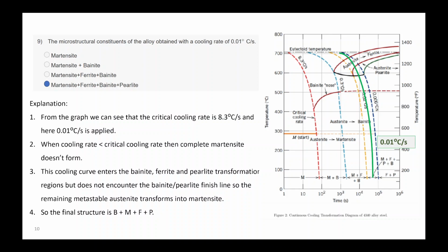Ma'am, in that metastable state, the statement was actually given: it is actually a non-equilibrium state, but with a very long time for changes to occur. When we take that martensite is actually a metastable state, isn't it? So in that case, even if we keep it too long, we'll still have martensite, isn't it? The martensite is actually not changing to any other phases.